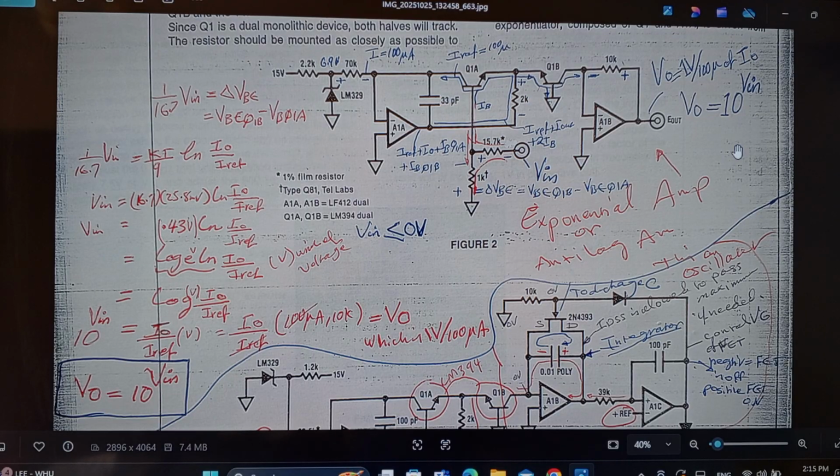In order to understand the circuit, it's better to apply numbers to it. And like we said before, we are always looking for the difference between the VBEs in order to take that difference, convert it back to a current, and feed it to an amplifier or to an op amp. So that's what we are doing. And we're going to start by applying 60 millivolts in here.